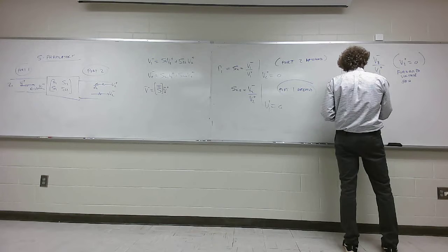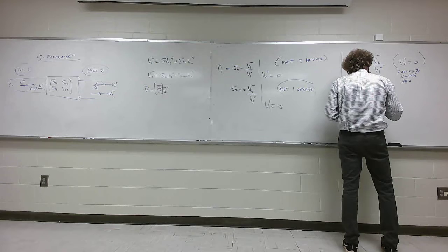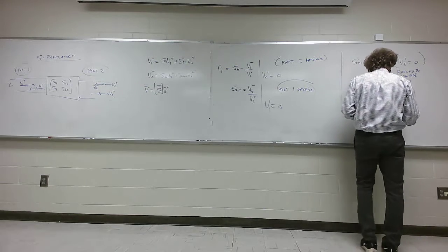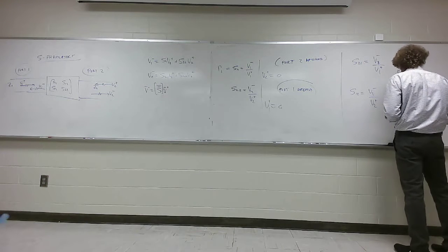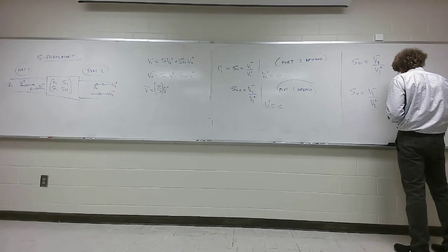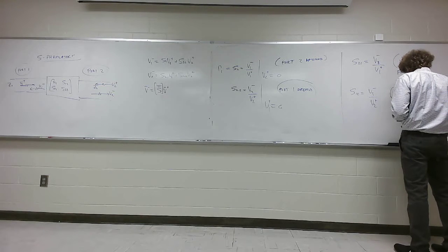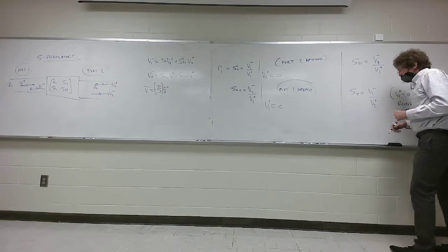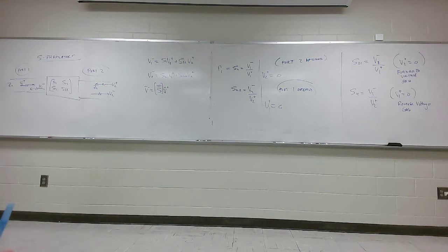So what do you think S12 is? Well, that's V1 minus over V2 plus, and this is assuming V1 plus is 0, and this is the reverse voltage gain of the system. Are y'all with me? So really we're talking about terminologies that you're familiar with, only S is not something. I believe S, and I'm not certain of this, came from system parameters, all right?